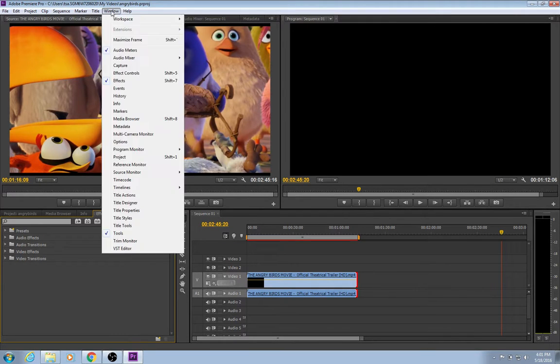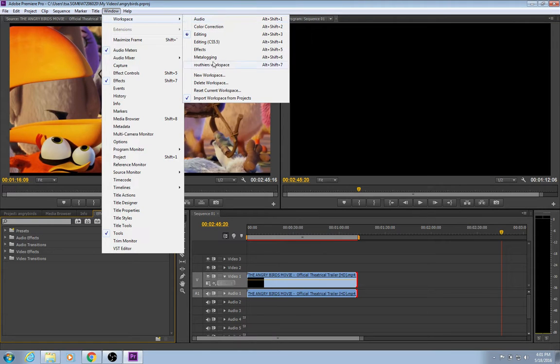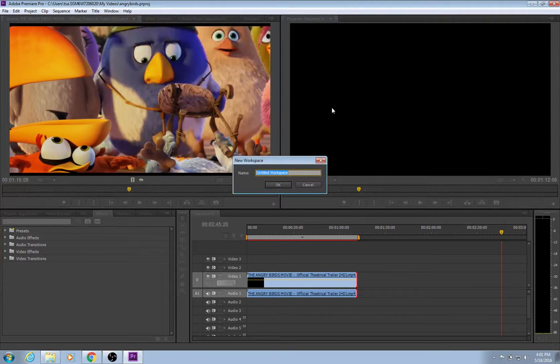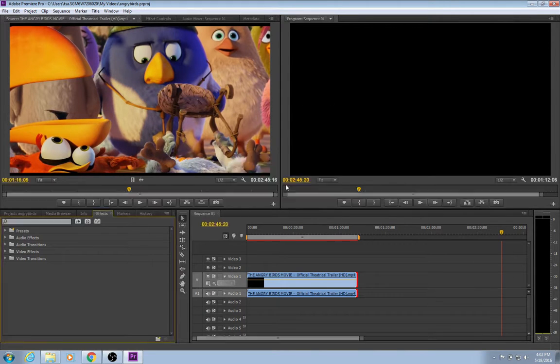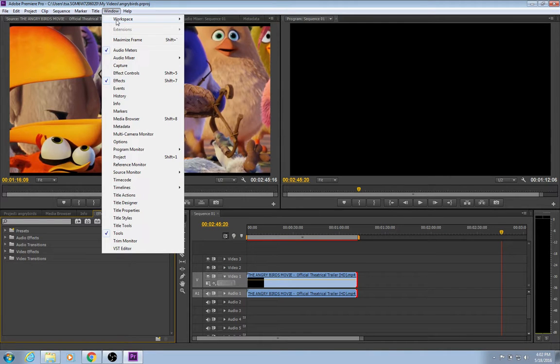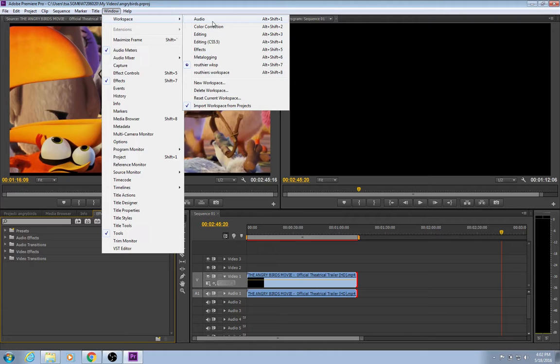So you go Window, Workspace, and then if the test asks you to create a new workspace, you just click on it and say, whatever, I'm going to call this Routhier WKSP. So there's the Routhier workspace. I'm going to say OK. And now this is the Routhier workspace. I didn't change the name of the file. I just created a workspace. If you go into Window, Workspace, you'll see I created this Routhier workspace right here. You can see previously I created another Routhier workspace.